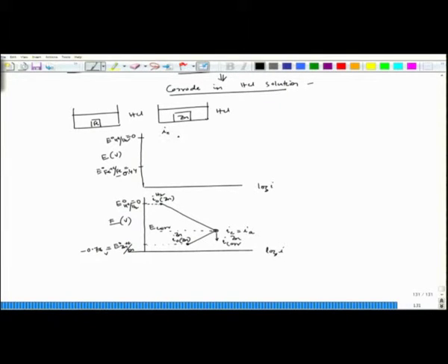So, this is I0 of the hydrogen reaction on the iron surface, and it is almost on a similar level. This is I0 of iron on the iron surface. They will have their own mixed potential when they are dipped separately, this case and this case.